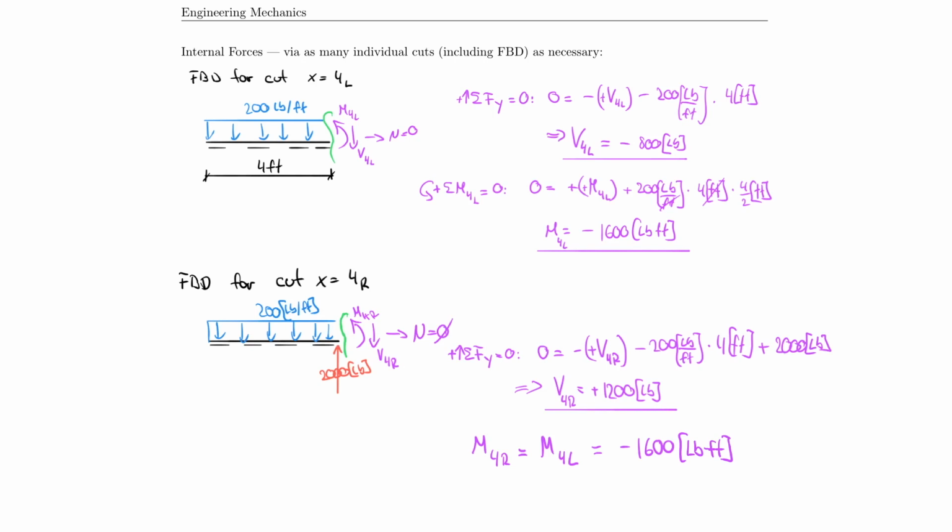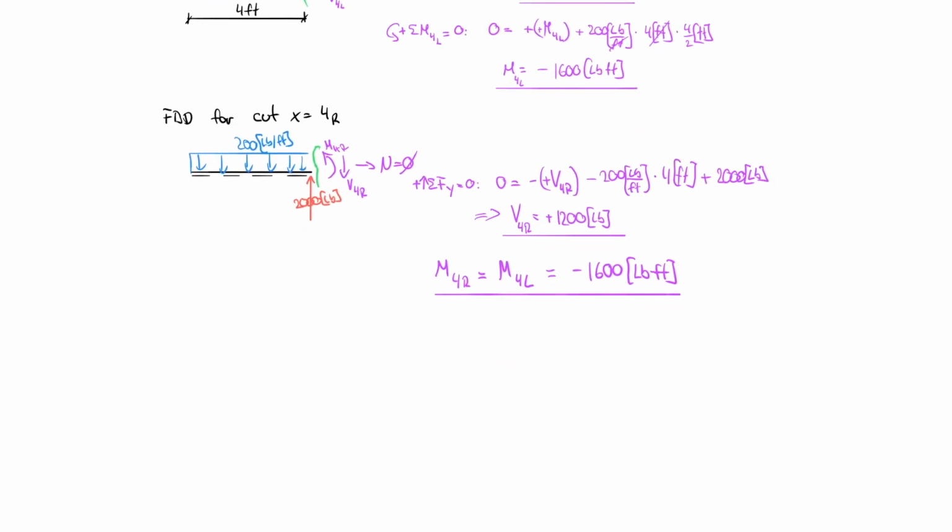And it's one thing to calculate the values. You actually need to understand the shape of the diagram, and that's again why I suggest that you make another cut maybe here and here so that you understand how you start from here to get to this point. I of course can take shortcuts because I've solved so many problems before. I've gone through the educational experience that you are currently going through, and that is why I am able to explain that to you and why I can do this fast. You should not fall into this trap of just doing this if you are puzzled, right? If you already have the answer, by all means, you don't need to do more work than necessary. But if you could not draw the diagram based on these numbers right now, I would encourage you to find the internal forces maybe at 2 feet and then maybe at 0 feet so that you can actually build up the diagram yourself.